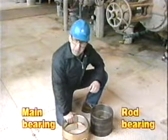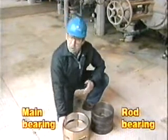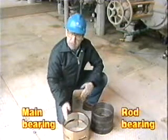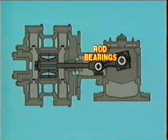Now let's talk about bearings. Compressors have main bearings and rod bearings. Main bearings support the crankshaft at the center line of the frame. Rod bearings, located at each end of the connecting rod, allow the rod to rotate smoothly with the motion of the crankshaft. Both main and rod bearings are types of sleeve bearings. Once again, lubrication is vital. In fact, lubrication must be continuous to keep friction minimized.